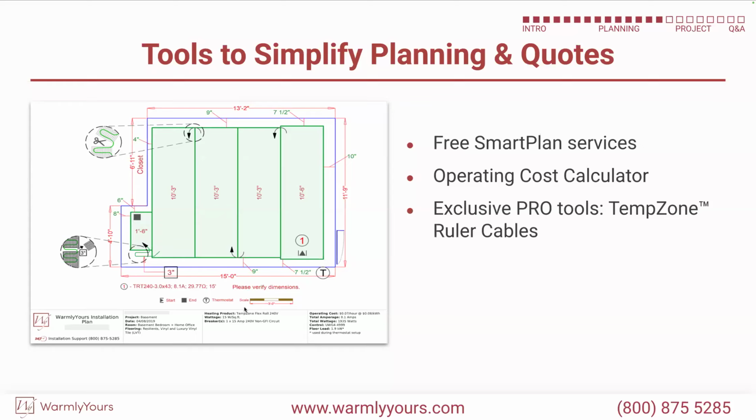Yeah, and people ask, well, how many watts is it going to take? We'll tell you. As soon as we get your drawing done, we'll tell you the watts, we'll tell you the amps, and we'll also tell you what size breaker to go out and buy. So it takes all the mystery out of it. The main thing is that the T is where your thermostat is, and that's where we're always going to start the design. If you tell us that the T is going to be in the upper left-hand corner, we're going to redesign this room so the lead can reach that way. The lead is only 12 or 15 feet, so I can't put a thermostat on the other side of the room and get the lead all the way back to it. So we're definitely going to know the beginning of the mat is a triangle, the end of the mat is a square, and the T should be somewhere in the near vicinity of the triangle.